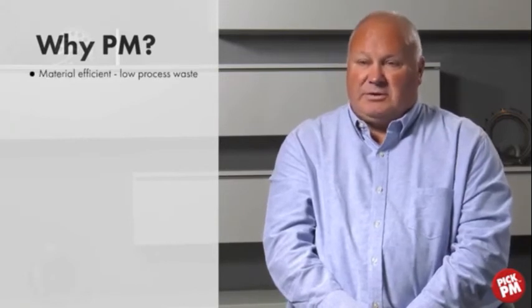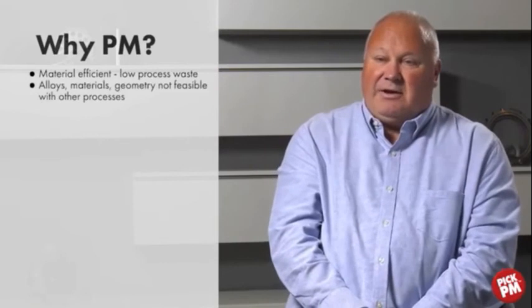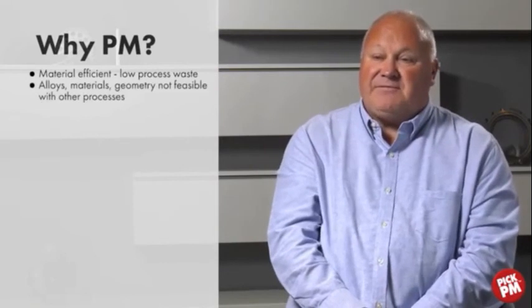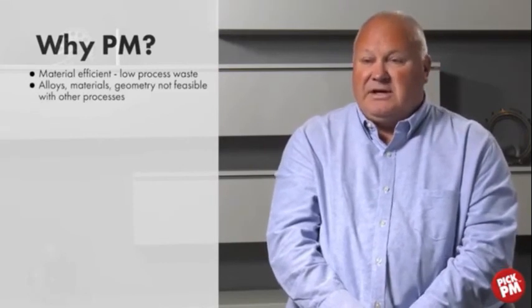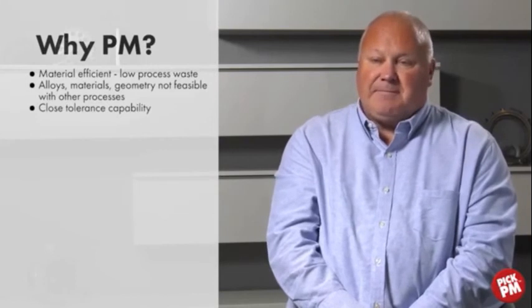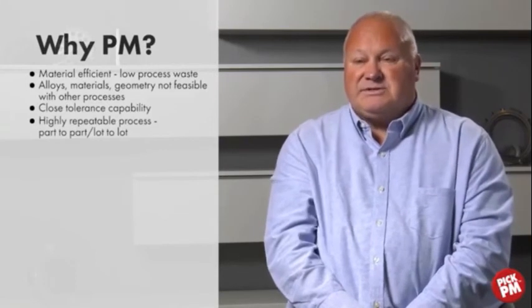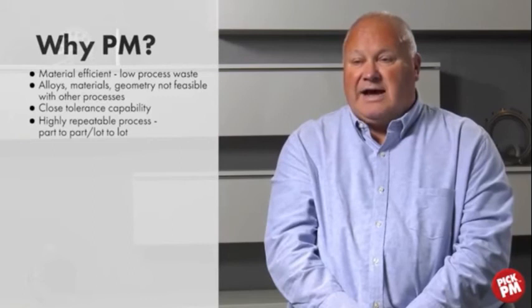So we ask the question, why PM? It's the unique shape capability and a host of properties that provide users with creative solutions. Powder metallurgy is a very material-efficient process with low process waste, and it offers alloys, materials, and geometry that are not feasible with other processes, close tolerance capability, and highly repeatable processes from part to part and lot to lot.